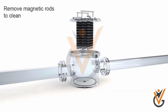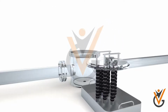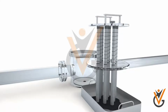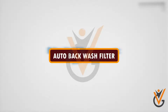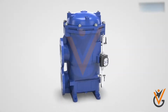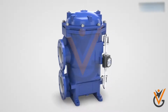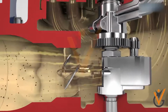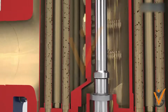Magnetic filters are often used in lubricating oil systems, where a large permanent magnet collects any ferrous particles which are circulating in the system. The magnet is surrounded by a cage or basket to simplify cleaning. Auto backwash filter. With this type of filter, when it begins to clog up, a back flushing process is automatically initiated so the filter cleans itself. The back flushing oil with the sediment from the filter is drained into the fuel oil drain tank from which it can be recovered and purified.